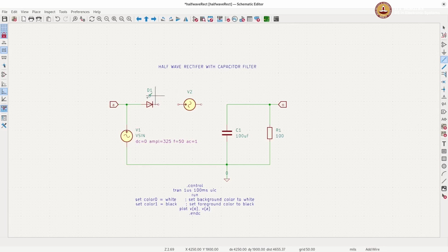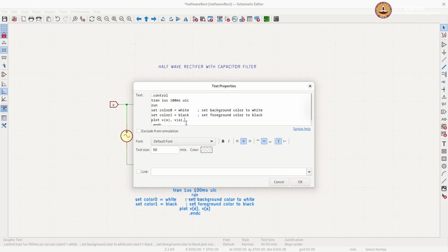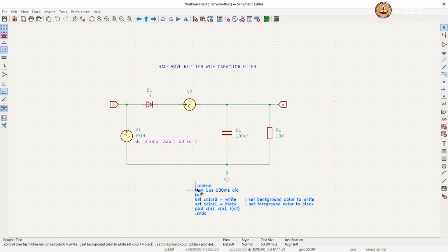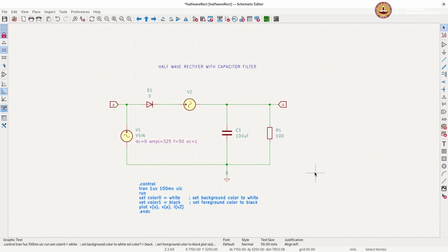I will go and pick the wire symbol and connect this up. So current through V2 will give me this branch current. So wherever I want, I can put a 0 voltage source and use that one as a current sensor. So let me say I want to measure the current through this branch. I will also include one more, which is I, current of V2. Current of V2 will give me that. Let me left align it. Yes. So here you have IV2 also being measured.